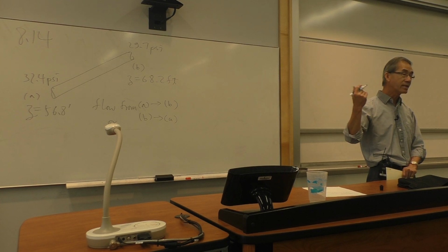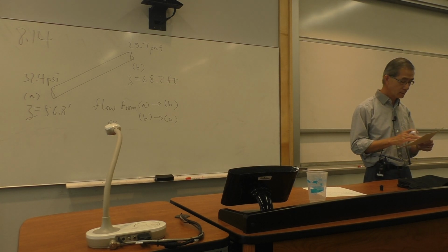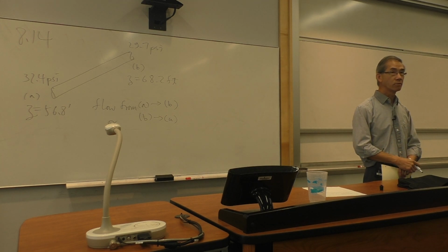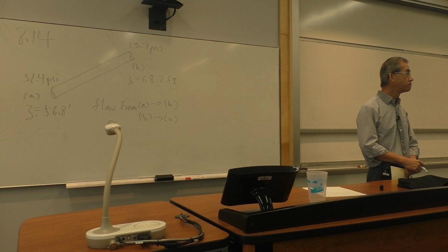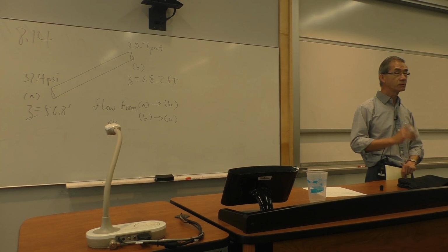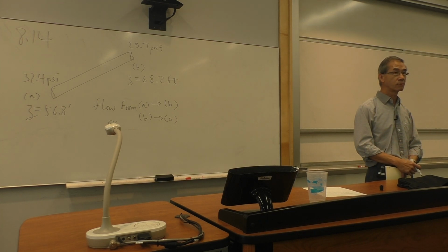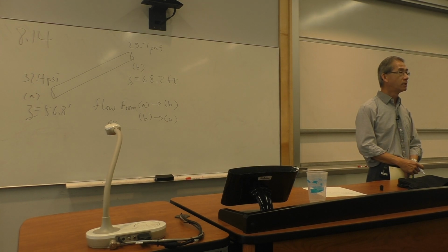If the problem didn't tell you that the flow is inviscid, it didn't tell you. It didn't say anything about viscous or not viscous. What are you going to assume? Moving forward for all problems now, you better assume it's viscous. And it's the same in the test. If you're not told, you assume viscous. Only time you use Bernoulli is when you're told to assume it's inviscid. Make sure you know that very well because it can be a trap.